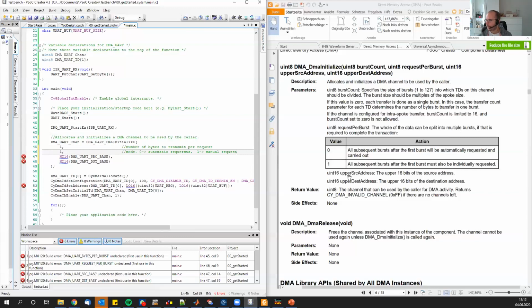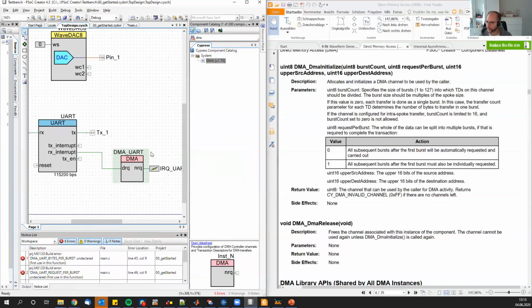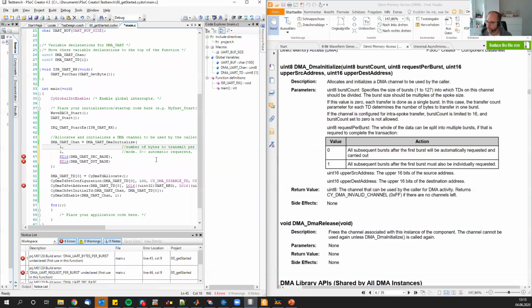Professor, I just have one question on this. If you want to transfer 4 bytes, like a UINT32 data, still the number of bursts should be 1? No, then you would have 4. For every byte of the 4 bytes, we will have a burst sent, like the second configuration mode. It is not like we trigger it once and then it will automatically do this 100 times, but for every request, we will just copy this number of bytes.